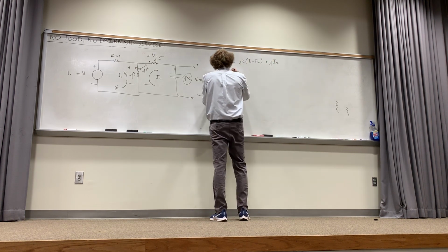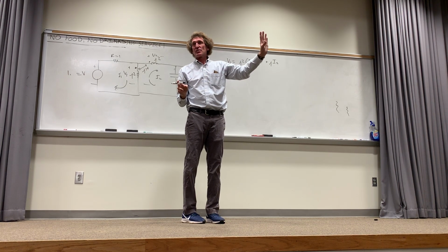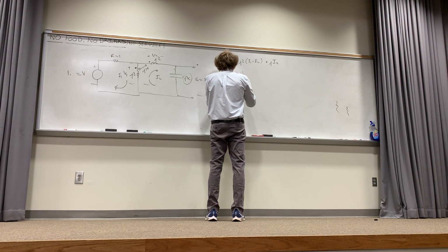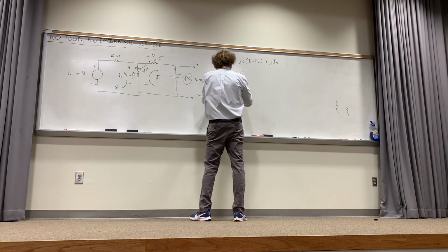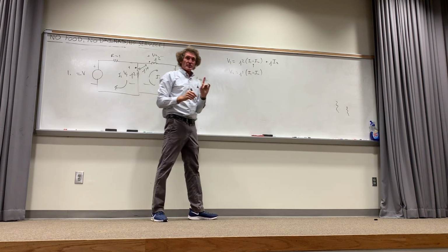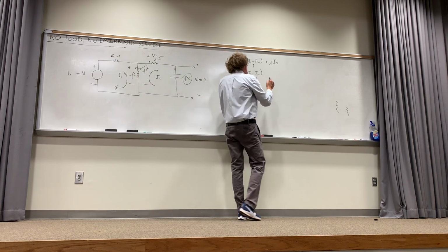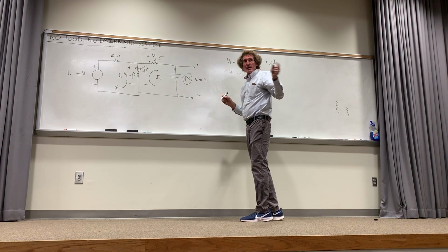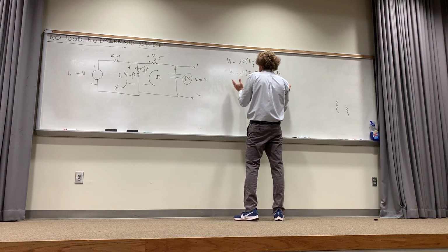So that's V1. V2, on the other hand, now I always try to put I1 as the first term, so it's the mutual times I1, right? And the mutual is J1, right? And it's times the actual value of the current flowing here, which is I1 minus I2, the same as the term right above it. Normally it's just I1. Plus, then it's the self-impedance, and that is J2, is it not, class? That's J2 times I2. Those are the two values.